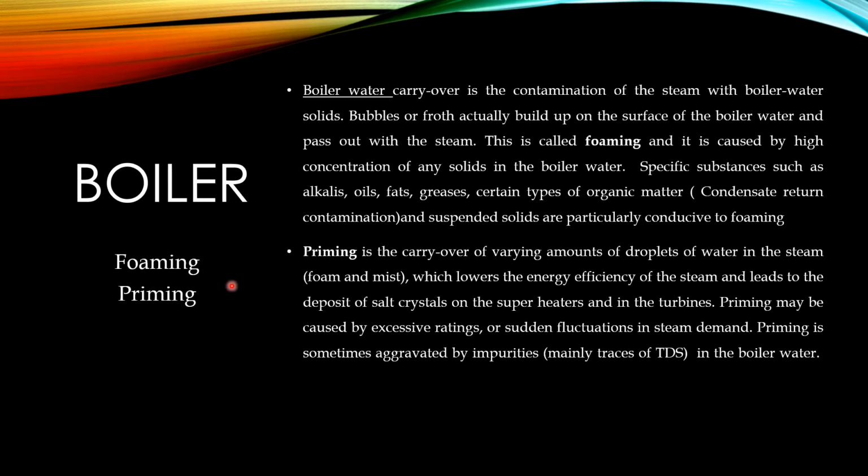We'll see about the reasons for foaming and priming. Boiler water carryover is the contamination of the steam with boiler water solids. Bubbles or froth actually build up on the surface of the boiler water and pass out with the steam.